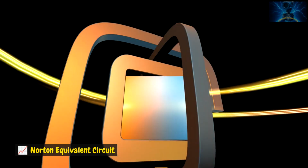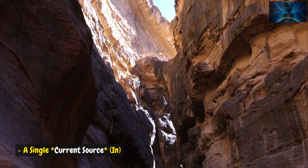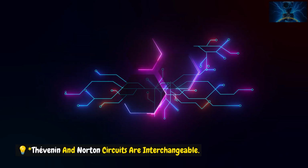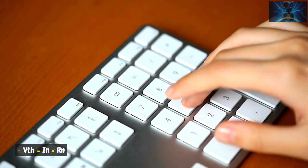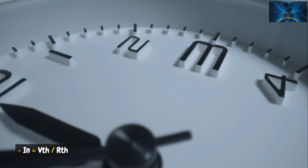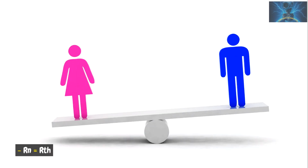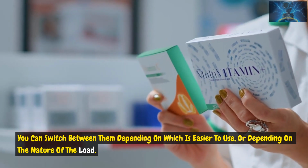Norton equivalent circuit. A Norton equivalent is the flip side: a single current source, IN, in parallel with a resistance, RN. And here's the kicker: Thévenin and Norton circuits are interchangeable. VTH equals IN times RN, IN equals VTH over RTH, and RN equals RTH. You can switch between them depending on which is easier to use, or depending on the nature of the load.